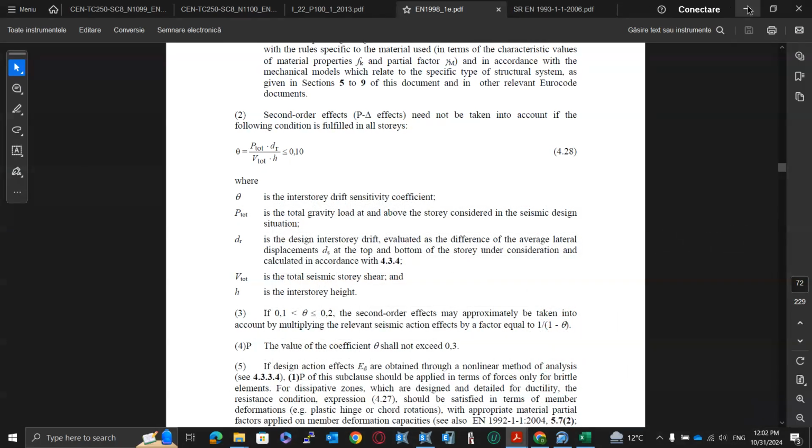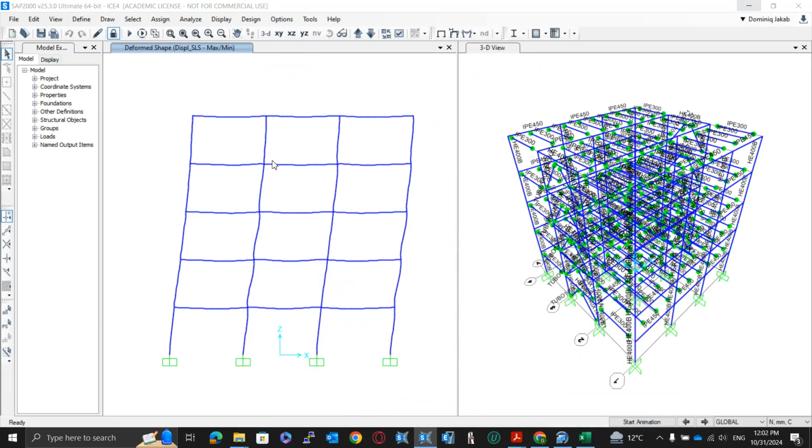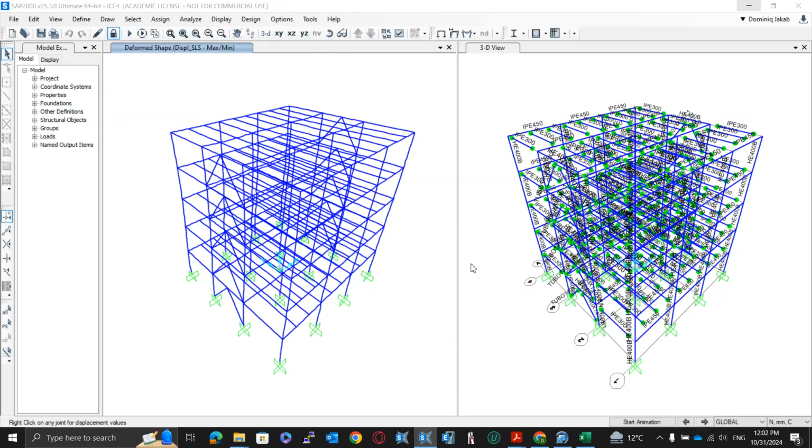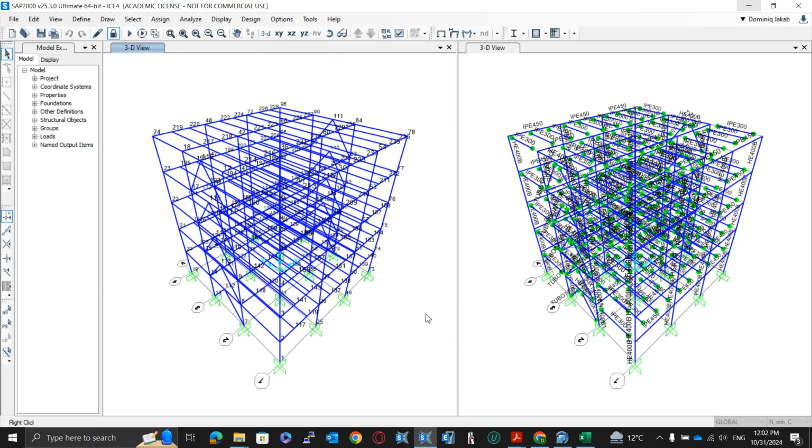The forces, you can take them from the diagram, and you will kill yourself if you have braces, because you will need to decompose on vertical axis and add them and so on and so forth. You can use section cuts, and I will show you how to perform 2 section cuts, okay?